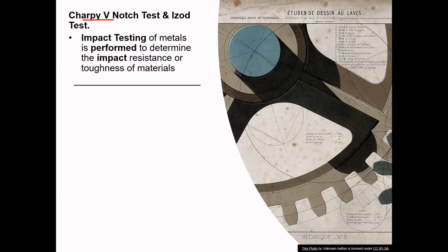These three tests are all essential to determine the same characteristic of a material, but differ in the orientation of the test sample, which causes the sample to be stretched in a different direction, and involve a weight released from a known height colliding with the specimen in its test fixture.